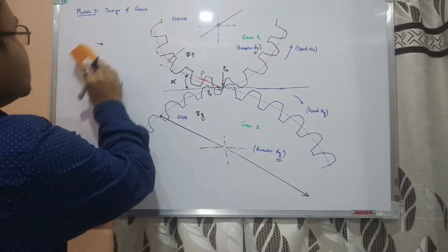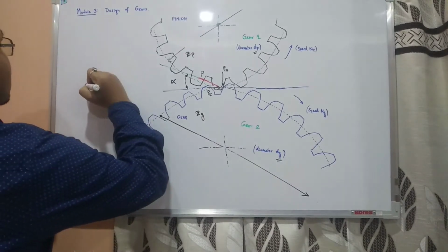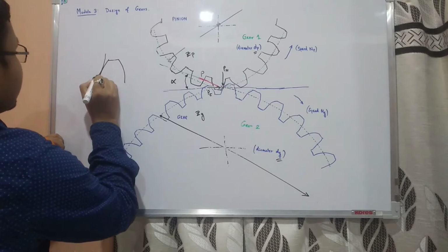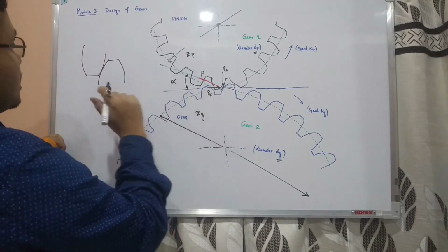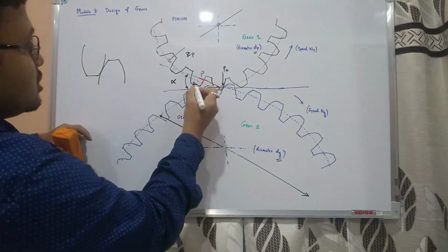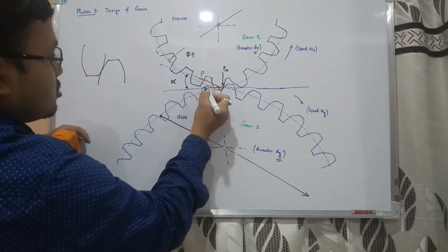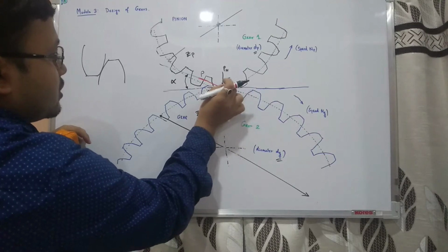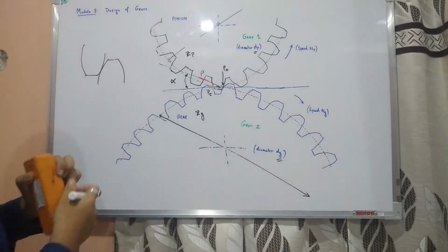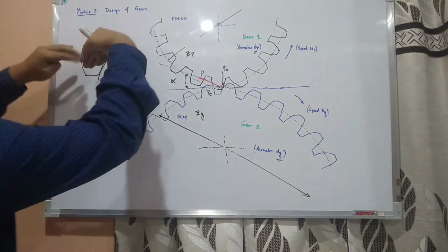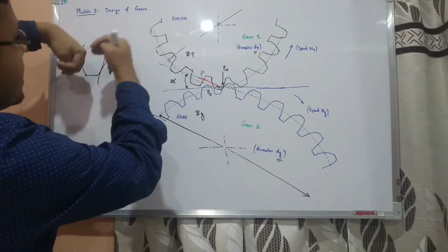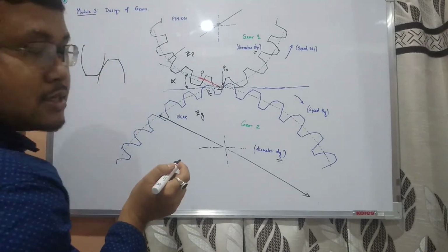Now we want the gears, this is one tooth of the gear, this is another tooth of the gear. When they are in meshing, from the beginning when they start just touching each other till they leave, this one is approaching this one, it will be touching it, and after passing through this point, it will leave the teeth. At that point we want them to purely roll over each other, rolling, no sliding. We minimize the sliding.